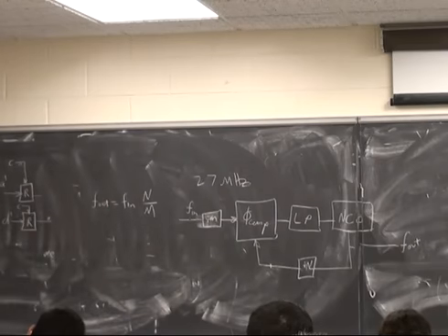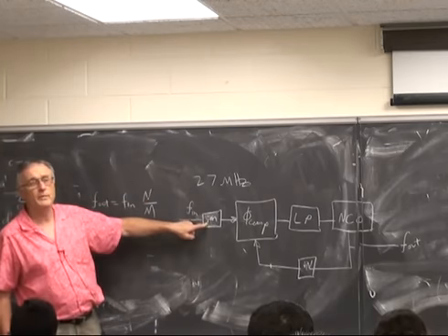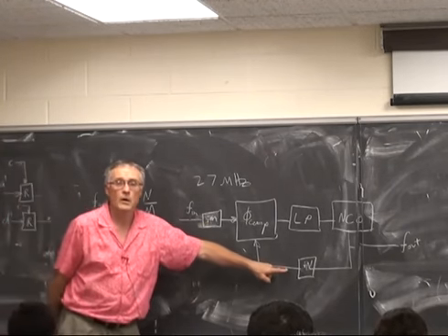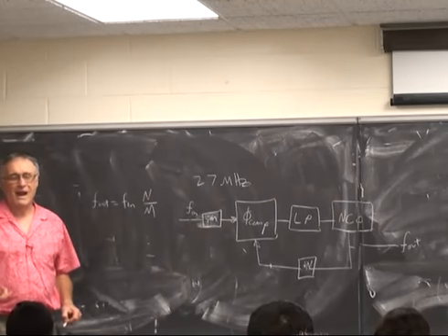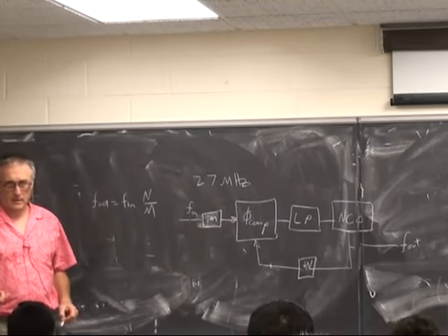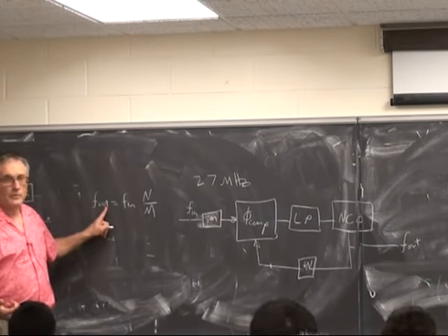And so, depending on the depth of the counters, how many bits of each of these you are saving, you can make any rational valued frequency based on a given input.